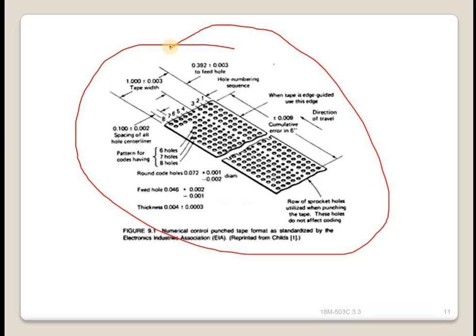In the manual method, the tape punch machine operates in conjunction with the typewriter-like machine, early versions of which were called Flexowriters. Each character typed on the Flexowriter is converted to a set of hole patterns in the punched tape. With the computer method, the tape punch machine is controlled by the computer according to high-level instructions that have been prepared by the part programmer. The end result with either the manual or the computer method is the same: a punched tape representing commands to operate the NC machine.